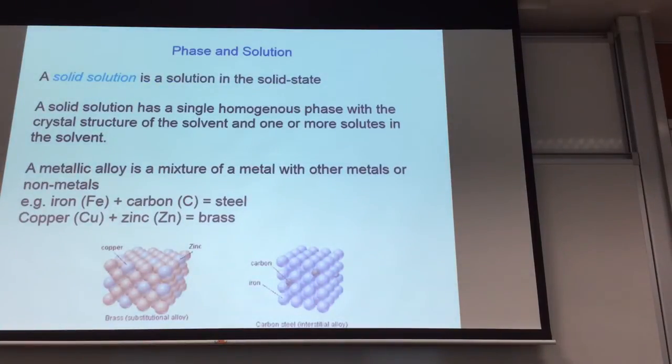A solid solution is a solution except that it's in a solid state. When we talk about metals, alloys are solid solutions. Basically, the solid solution, like a liquid solution, is a single phase. You have the base material. Let's say steel: the base material is iron, but you have some other metals in it. But this is still considered a single phase, with the same chemical properties.